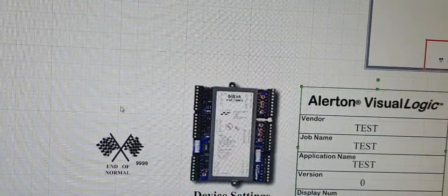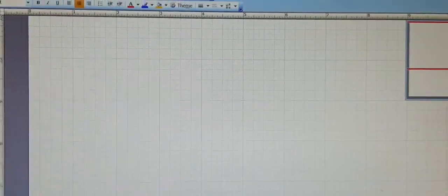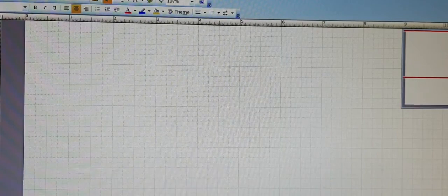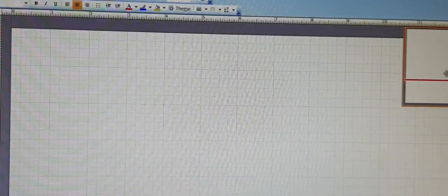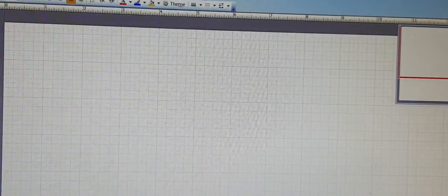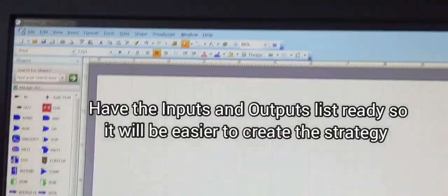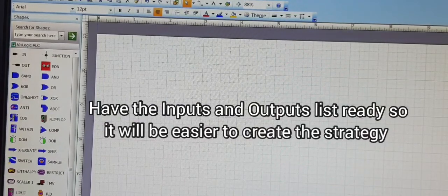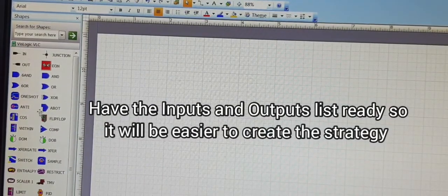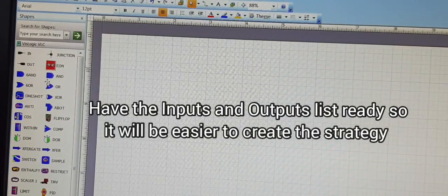You have to start creating your own programs, so that way you can learn better. When you're starting out fresh, you're just modifying the existing programs. It's important that you create your own programs also. It makes it easier. So for our AHU, let's create a program for turning on the fan. I'll show you what we need to do. For a fan, we will need to give the command to the fan, so we have to consider the safety conditions.